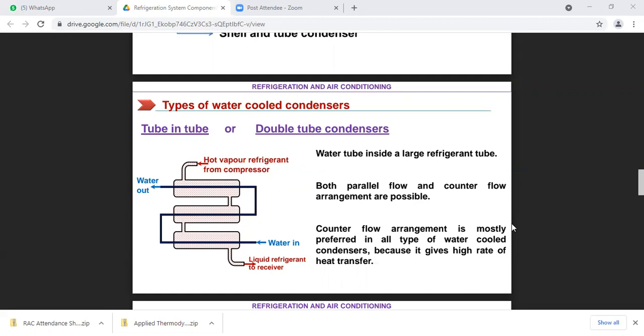This double tube type condenser finds its maximum application as a booster condenser for meeting peak load demand in conjunction with the chassis mounted air cooled condenser. They require a separate receiver for storing the condensed liquid. The size of the liquid line between the condenser and the receiver should be larger than the liquid line leaving the receiver, to permit free drainage and allow the recondensation of the entrapped vapor.